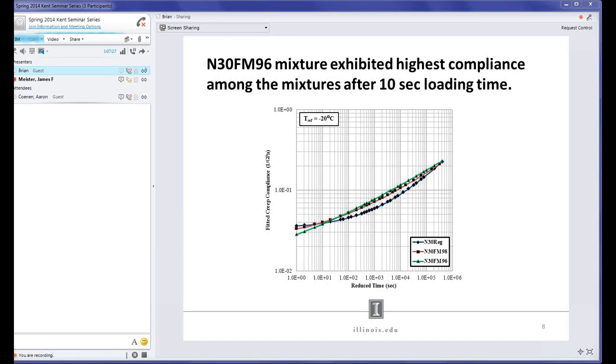And then in terms of the ILLI-TC results, the reason why I didn't show those is because we didn't find any issues with any prediction of thermal cracking. We didn't have any situations where we actually even reached a thermal event that would cause a crack to initiate, which was a good sign for these mixes. And we used the Chicago climate and this input information.